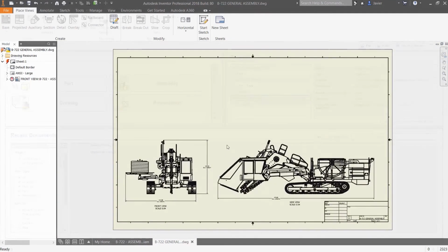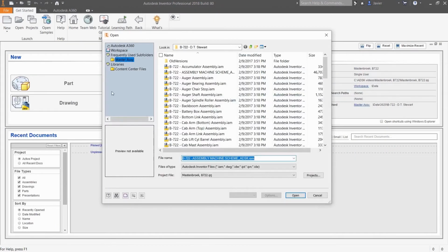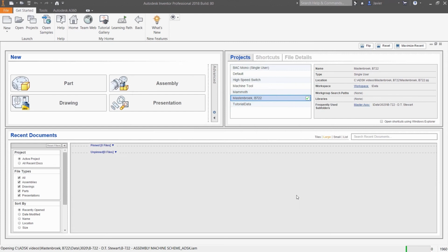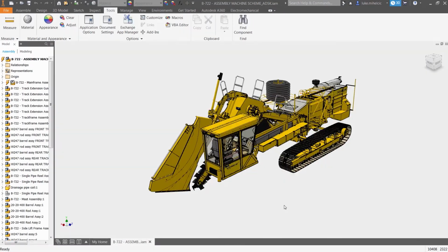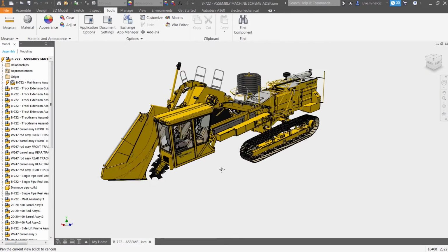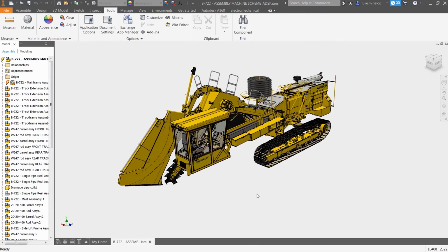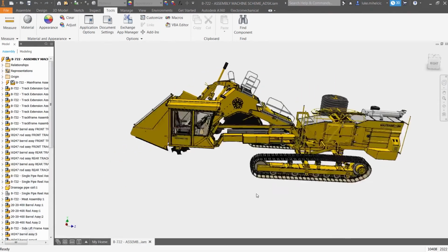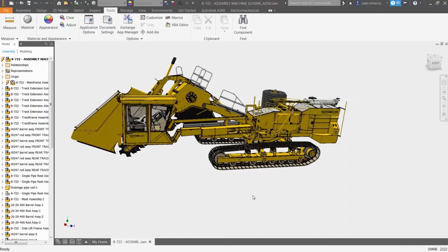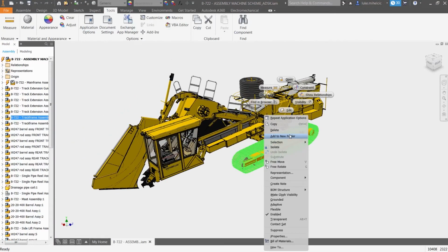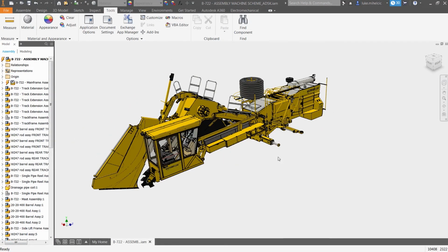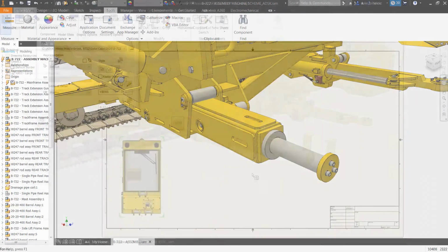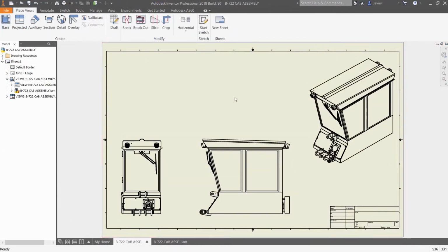So starting right away, just through File Open, you have the quick drop-down menu to load in full or express mode. And if you haven't used express mode in a few releases, I encourage you to take a look at it. It loads the needed geometry to get the model up on the screen. And as you start selecting or editing geometry, it loads it fully as needed from a part or a component standpoint. In Inventor 2018, we've made it much more responsive with selection and on-screen graphics.